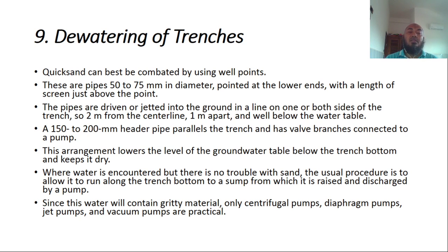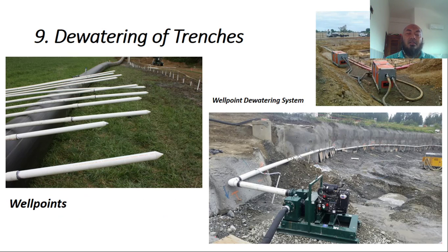When water is encountered but there is no trouble with sand, the usual procedure is to allow it to run along the trench bottom to a sump, from which it is raised and discharged by pump. Since this water will contain gritty material, only centrifugal pumps, diaphragm pumps, chain pumps, and vacuum pumps are practical.